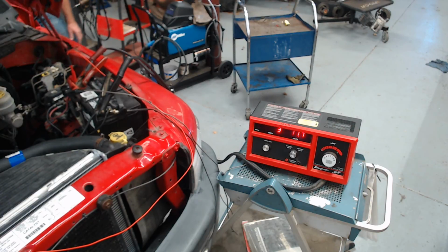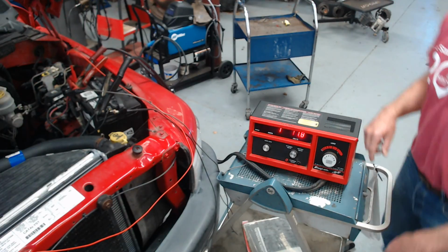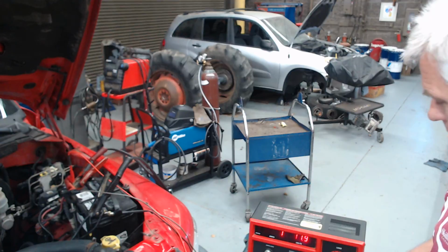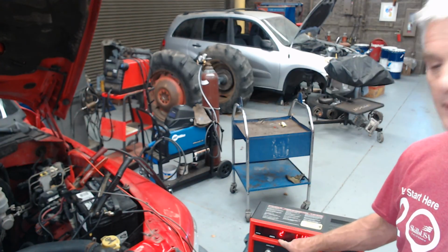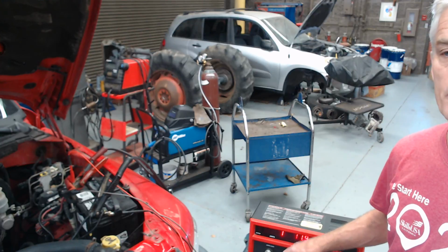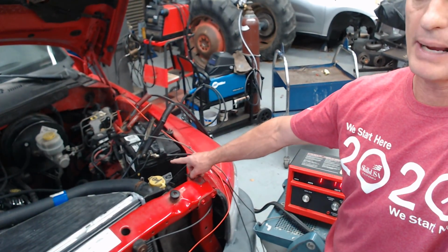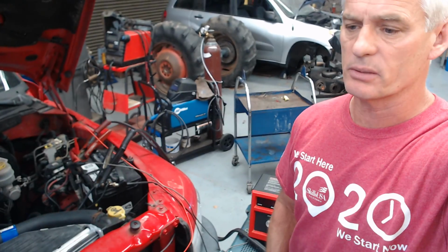Okay, so I saw 10.4 volts at approximately 156 amps. That seems just great. It was stable. The voltage was stable at 10.4 volts, and the current draw was about 150 to 160 amps. That should tell you guys that the health of the battery is good because you can hear the cranking speed. The health of the starting system is good, etc.